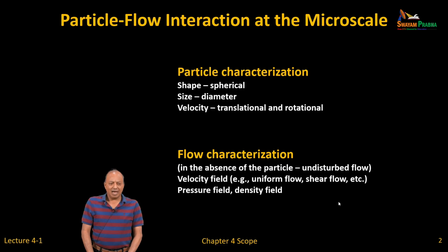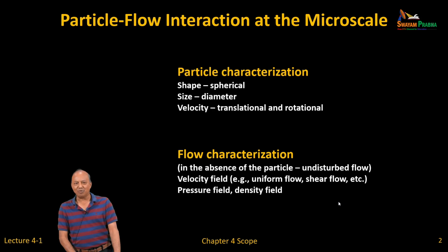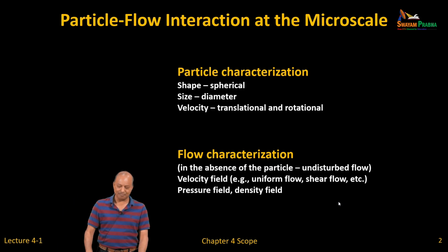Therefore, if we can't put all the grids, we want to have some formula for the drag. In other words, the momentum exchange, heat transfer between the particle and the surrounding fluid. So, we want a cheap way of calculating how the particle is interacting and talking with the surrounding fluid. So we are heading towards modeling with the knowledge that we can't put the grid. Of course, if you are doing a particle resolved simulation, you don't need to worry about this.